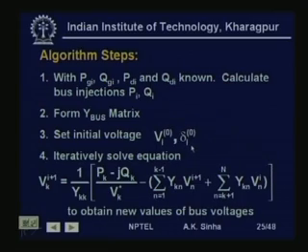Now, what we do is we use the iterative solution here, that is for I plus 1th iteration for voltage at kth bus. We can write this expression like this, and here the only thing that we are seeing is that we are using the most updated value.